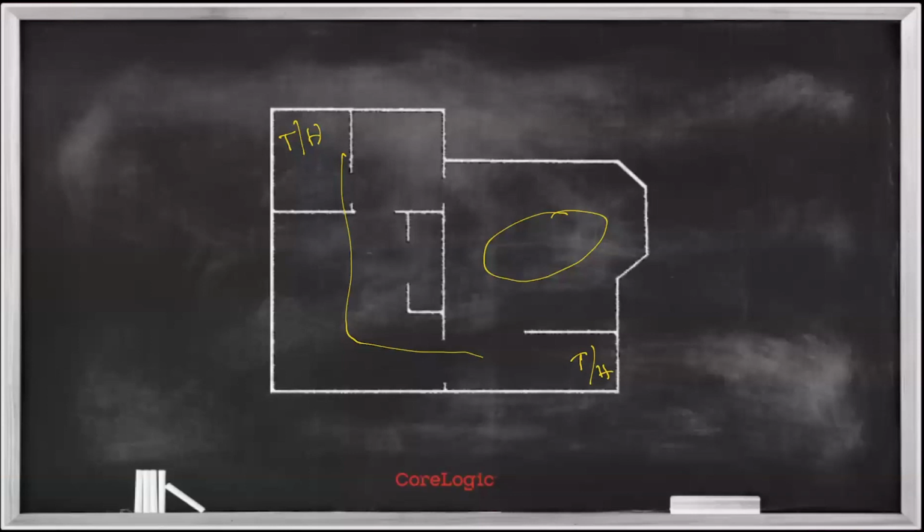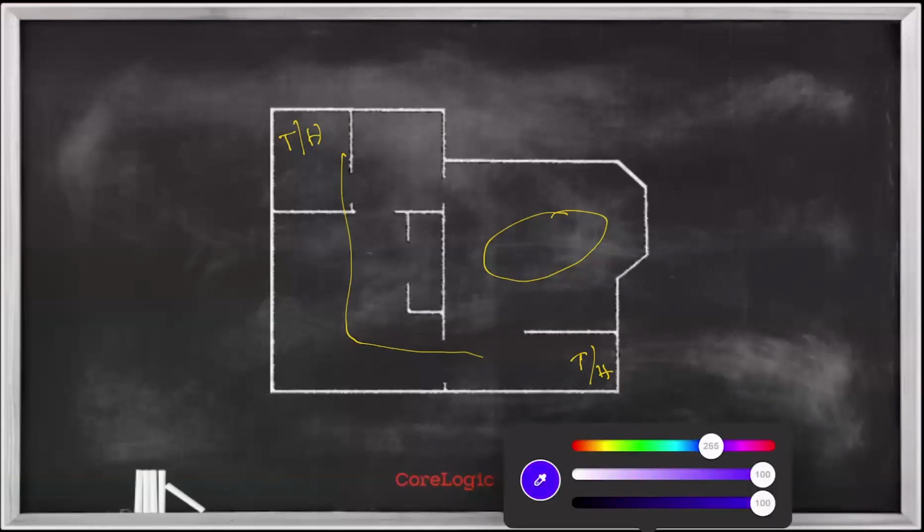I'm not concerned about tenths of a degree and tenths of a percent RH, but if you're any more than about 1 to 2% RH different, any more than about 1 to 2 degrees Fahrenheit different between those two extremes, then your circulation is restricted, right? And you have two choices at that point. I can either modify the way I'm moving air so that I get better circulation, or I can treat them as separate chambers, right? Those are my choices at that point. But what you're going to find is that in a standard floor plan like this, as long as air movement has been established properly, you're not going to find that substantial restriction to airflow. So I want to illustrate that a little bit because it's important.